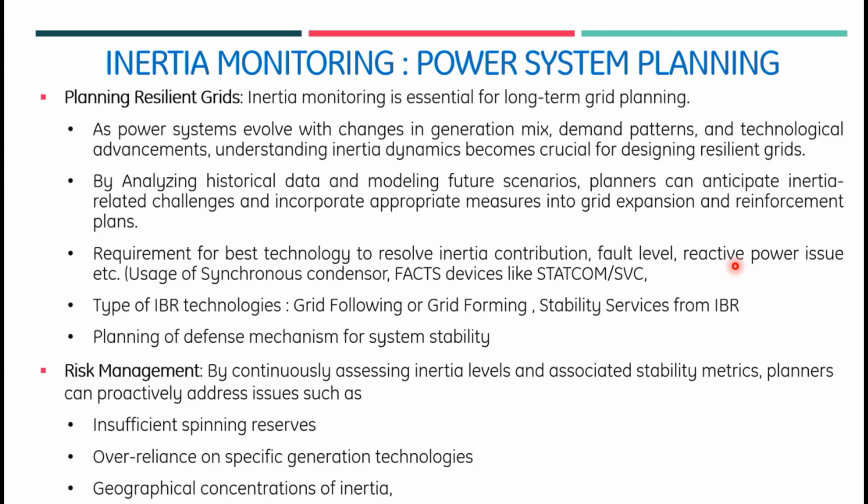Earlier there was no grid forming, only grid following was there, so everybody was utilizing grid following. Issues are increasing, so that's why grid forming inverters have now come. It is expected that they will help the system a lot with the challenges being faced: black start services, reactive resources, faster controls, and in terms of inertia and frequency response, all these activities. These kinds of stability services are expected from the IBRs.